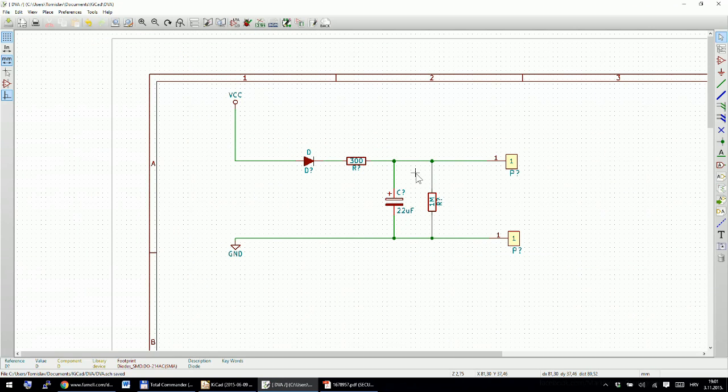So in this tutorial, first I will try to choose PCB footprints for the components. If you're a beginner, if you do not know what the footprint is, this is a very basic concept. Each electronic component has, let's say, like a shadow on a PCB, together with its contacts, which will be soldered to a printed circuit board. Virtually, a footprint is a way for your CAD program to know how to connect your real world component to your